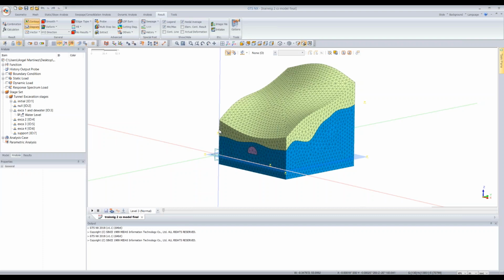If you really wanted to get into the details, you could start defining seepage boundary conditions and creating what would be a seepage analysis, a flow of water, and you could define a lot more control into that process. In this case, we're taking a big assumption and just saying that between stages the dewatering occurs, and now we can consider that the pore water pressure is below this table. So having done that, these are the same stages, and we ran the analysis.